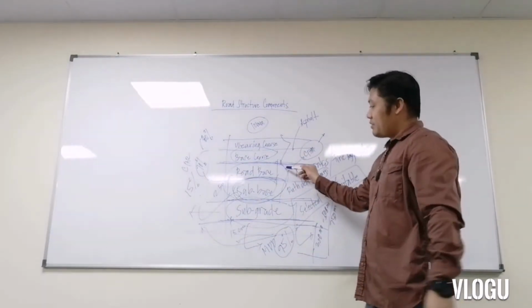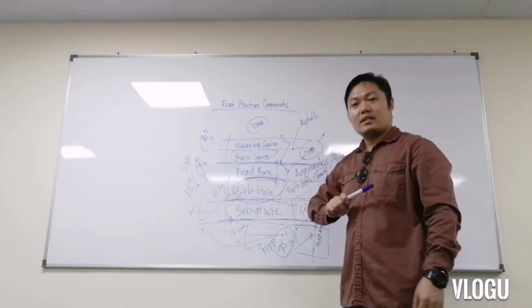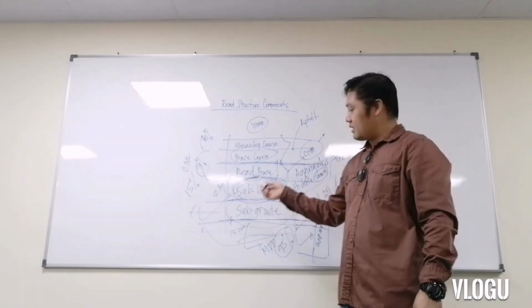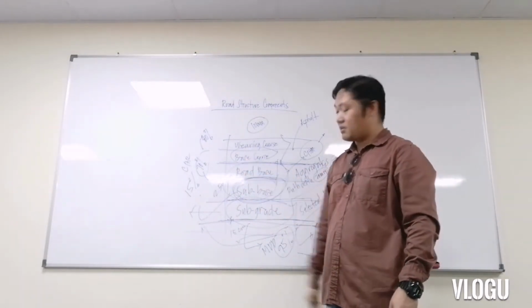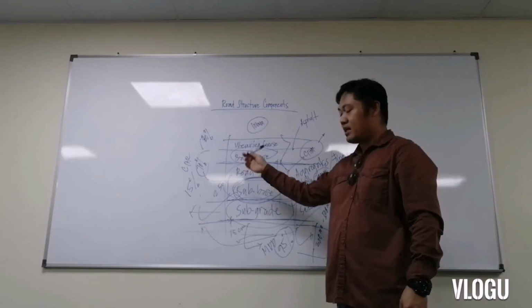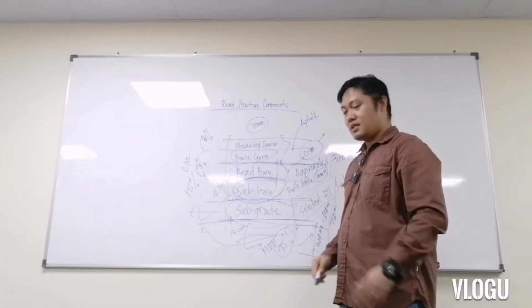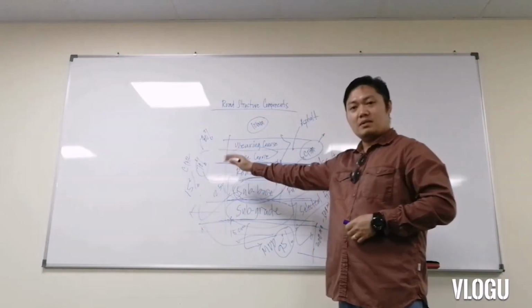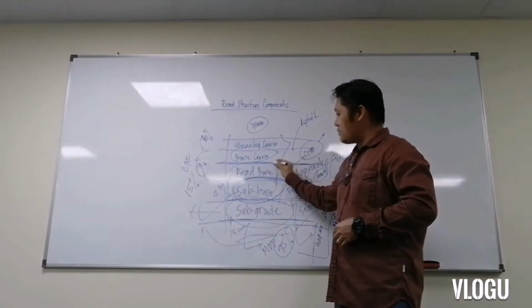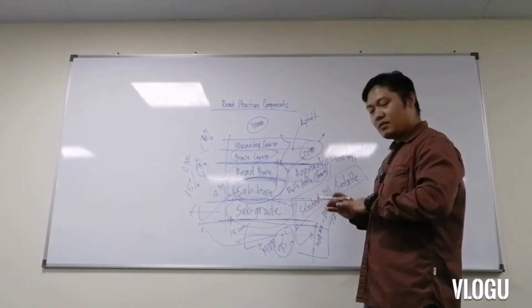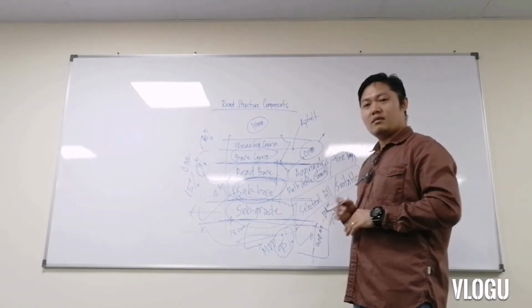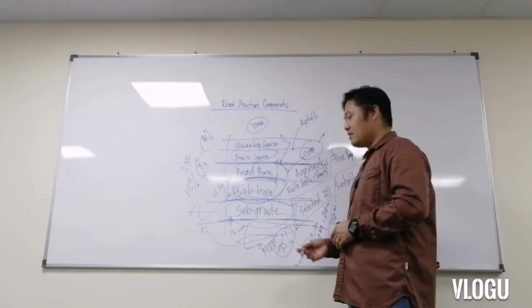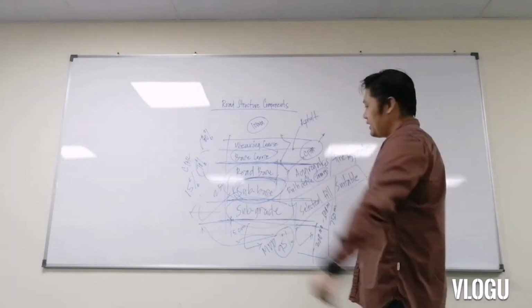So right now, since all the surface preparation has been done and all the utility clearances have been carried out, that's the time to start laying the asphalt base course. First, we check whether all the curbstone foundation has been done, all the curbstone has been fixed, and all the underground services have been verified, completely installed and pressure tested, or gravity tested, and so on.